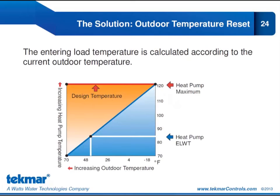The solution is an outdoor temperature reset control. This is where we're going to vary the entering load temperature based on the current outdoor temperature. So in a heat pump system, that means we're adjusting the tank target based on the estimated heat loss, or the outdoor temperature. And doing so will result in significant savings and improved comfort.